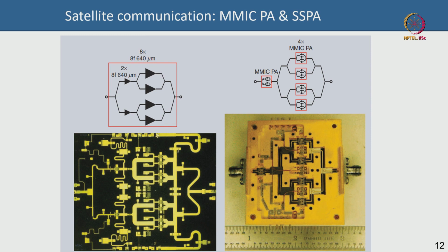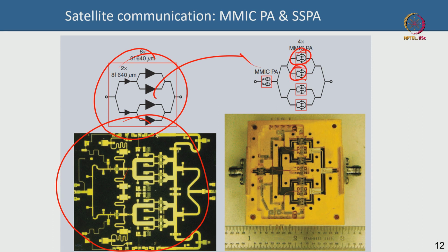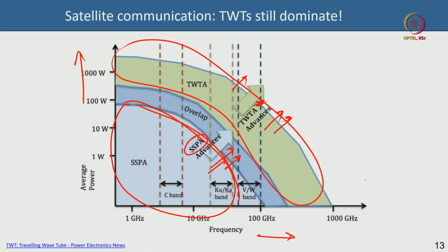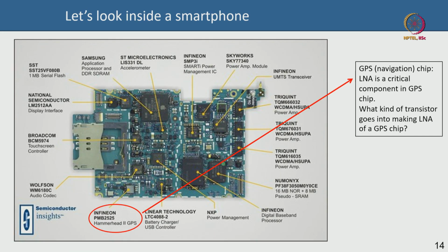This is the image of one power amplifier MMIC. Can you see that? There are all these transmission lines in yellow, all these power splitters, power combiners, baluns, transformers, impedance matching networks, all of which have to be very accurately designed by the way, based on a design kit that is provided to you by the foundry. This is a power amplifier MMIC, and many of these MMICs are combined here to get a large output power. So just keep that in mind, please.